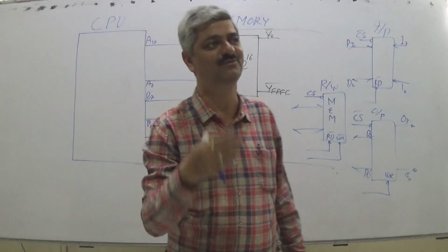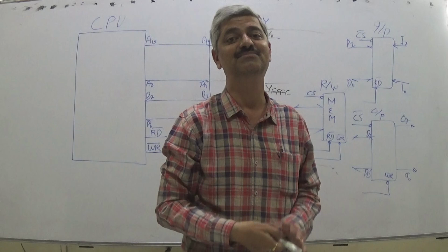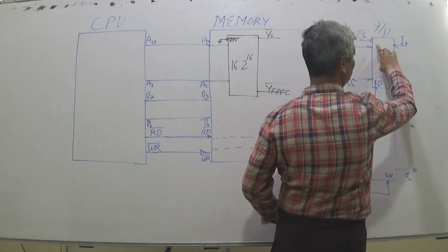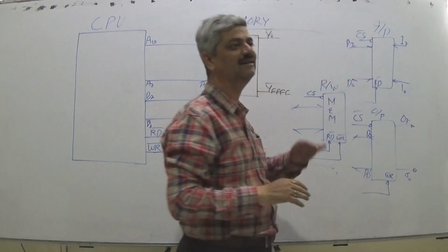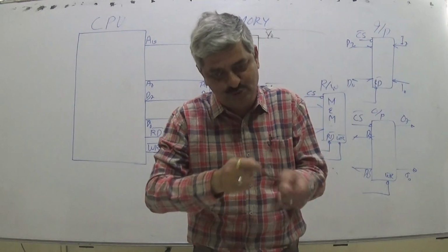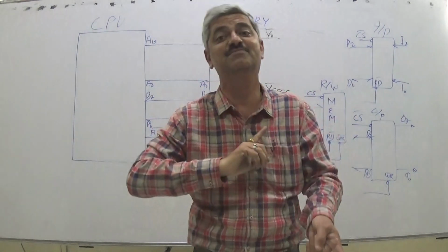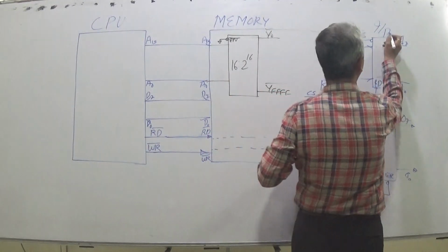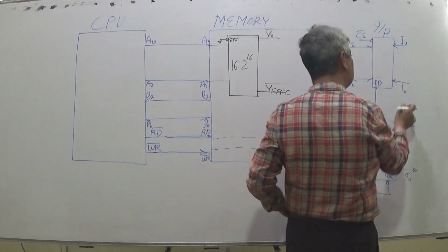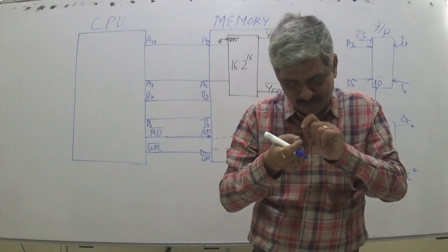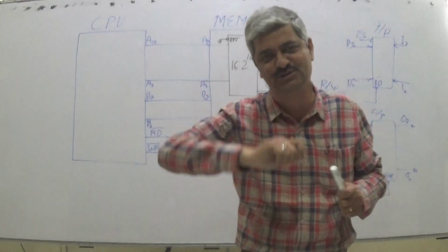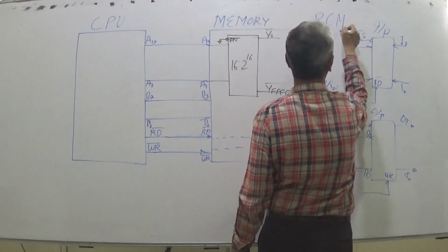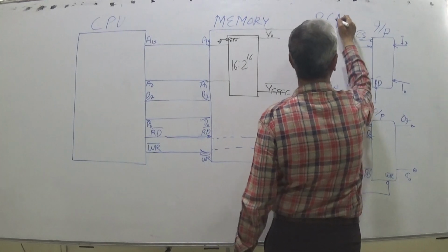Now the read write cell. When we say read write cell, we have to write, and then the data is available. Can there be something pre-written? In that case, there may be such input ports. The pins may come out, or the pins may be inside and put to some hardwired 1 or 0, which can be changed by some other technique. If these remain inside, with the option with the user to hardwire them to either 1 or 0, then it can be said to be a read only memory location.